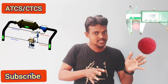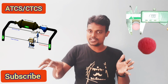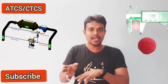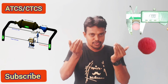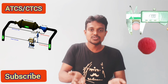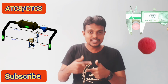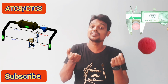So either the refrigerant releases heat into the water, or the water releases heat into the refrigerant. The heat exchange happens between the refrigerant and the water. In our present system, the condenser tube system, the auto tube cleaning system is generally used only in the shell and tube heat exchanger. In it, the tube contains water and the shell contains the refrigerant.